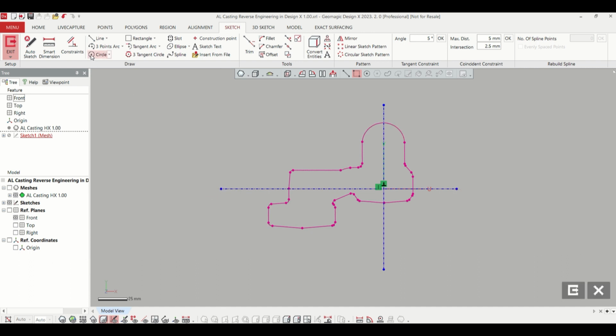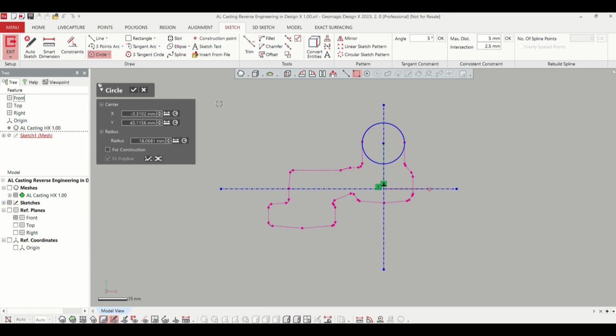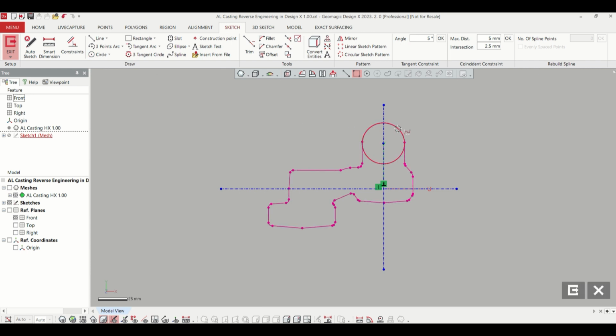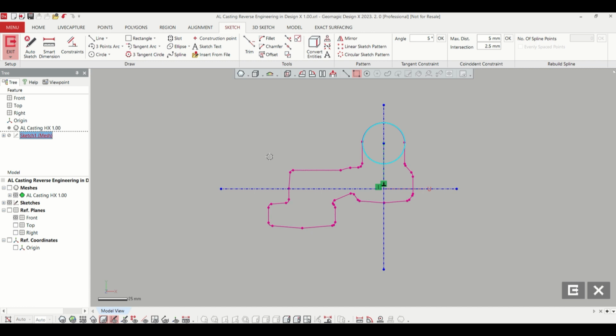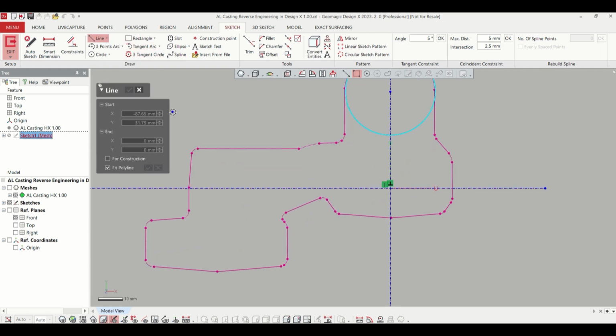Having done that, I want to create a best fit circle to the one that's shown here. And as you look at the details of that, we know that we want that aligned with the vertical axis. I really like to use dimensions that are rounded to a couple of decimal points. In this case, it looks like we're at 18.07 on that radius. So we've dialed that in, and we just want to go around the right-hand side of that vertical center line now and fill in the rest of the profile for what will become the basis of the revolve.